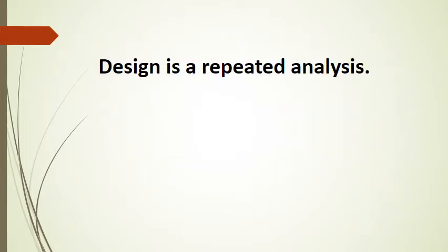Design is a repeated analysis. You have already calculated the load on the element you want to design. You perform an initial design by using some charts, past examples or your experience. You then perform the analysis to see if the design has enough capacity to take the design load. If the answer is yes, you complete your design. However, you may want to refine your design by saving some material or improving constructability. After you modify your design, you go back to perform analysis again. You repeat those processes until you obtain the solution you need.